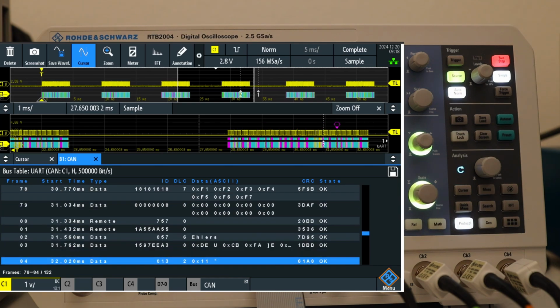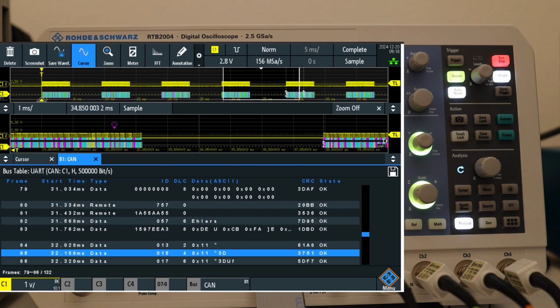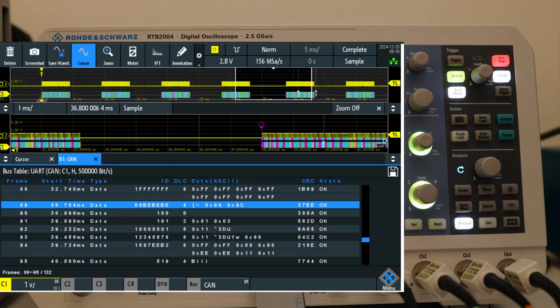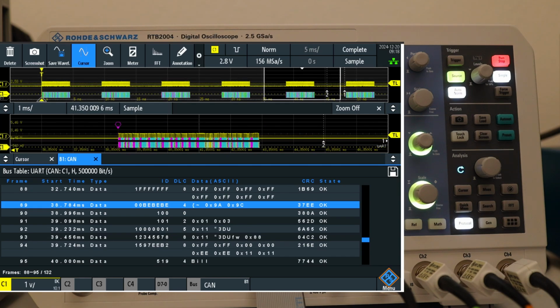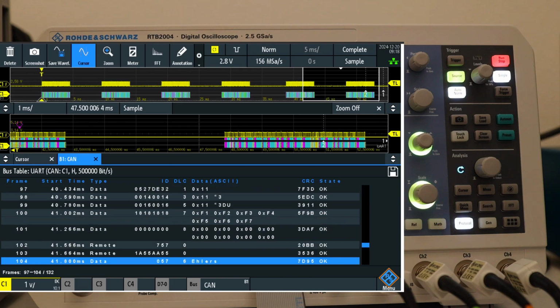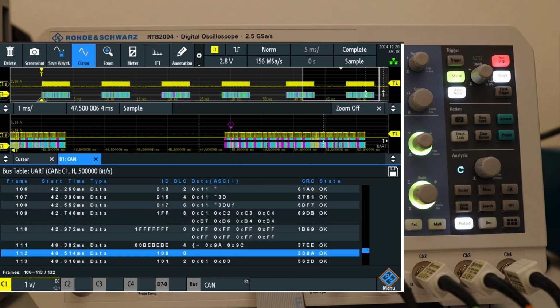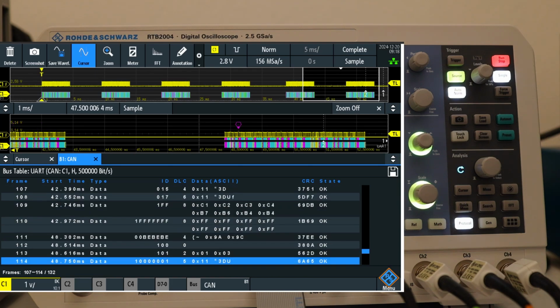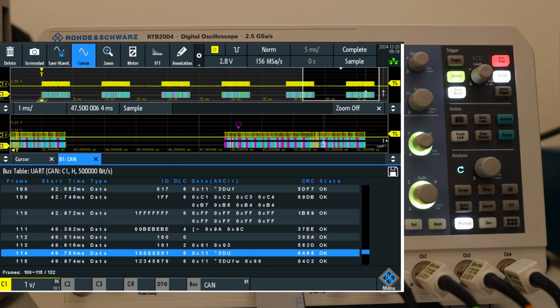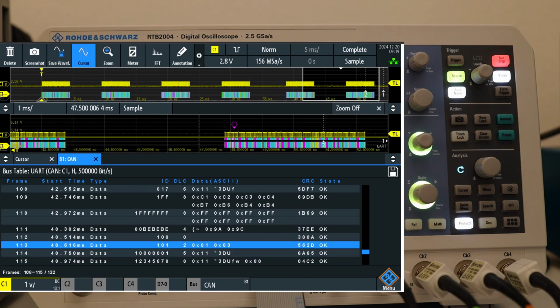We still didn't find that spurious or not so repetitive packet till now. We will try to find it. Okay, same packet BE, data content is also the same, CRC is of course also the same. So all these packets are exactly the same, and you see that this oscilloscope allows you to zoom through or exactly pinpoint where the packet is. Okay, so maybe we'll trigger on this ID 101. I'll trigger on 101 for the sake of entering fewer values. We still didn't find that spurious packet.